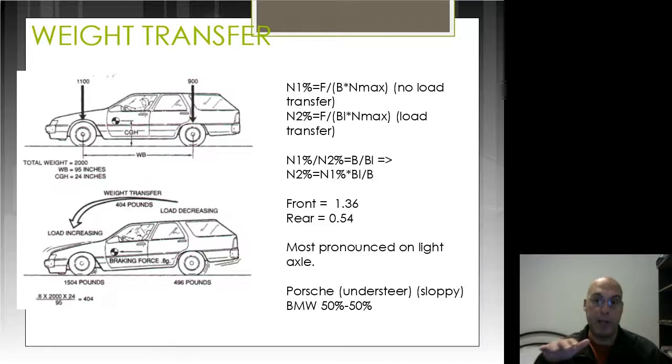The moment you get on the gas and transfer the weight off the front causes the car to understeer. And that can set up a difficult dynamic situation for which Porsches are very renowned. The same thing applies for mid-engine cars, which have a rear weight bias.